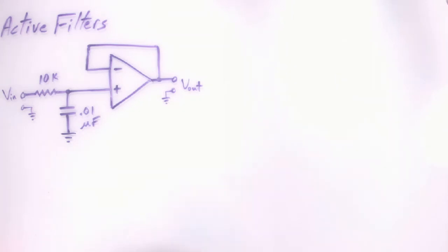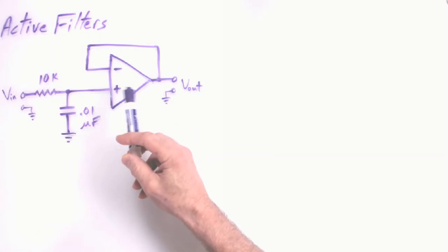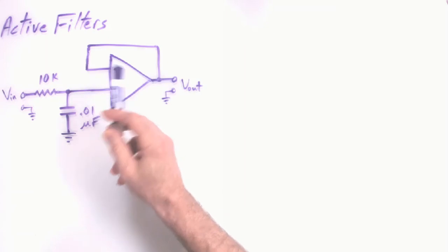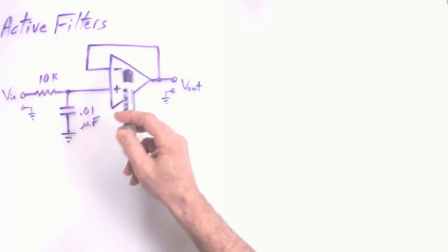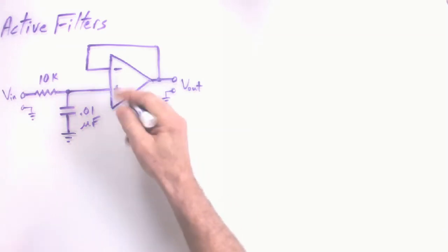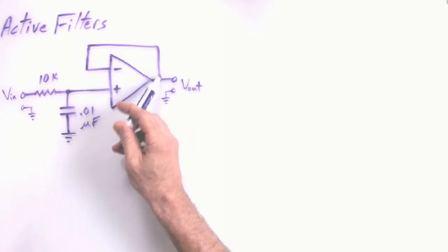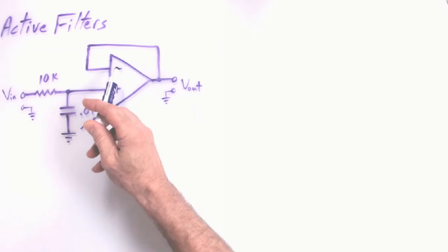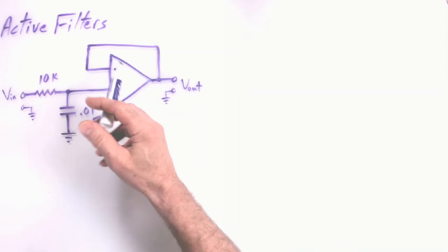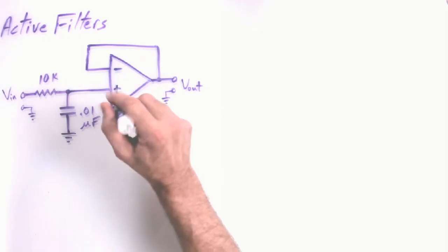One other thing I did want to mention about this type of circuit, where it's essentially a buffered voltage divider. Speaking of creating the voltage follower, the buffer, if you recall back to our introduction to op amps, a single resistor can also be used here to bring back the full amount of output back to the inverting input, and then hold the gain at just one, essentially no gain, right? Just unity gain, just one. So let's do that.